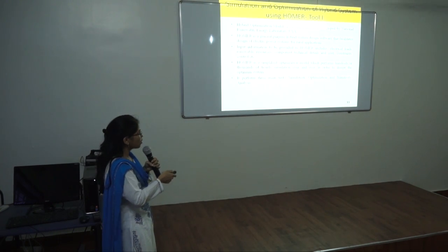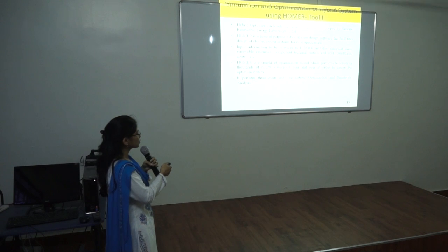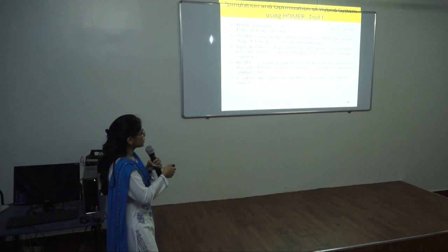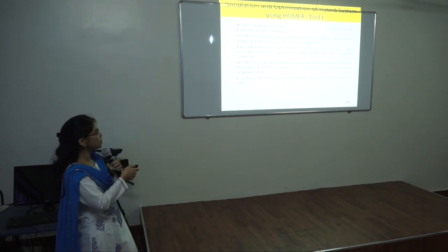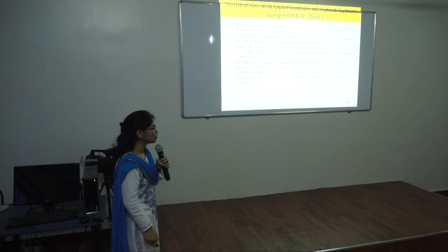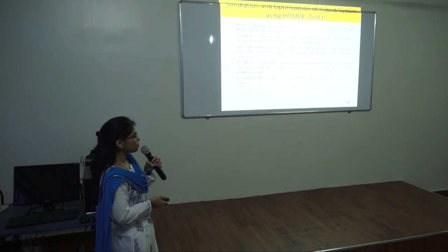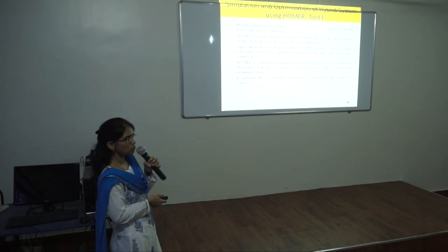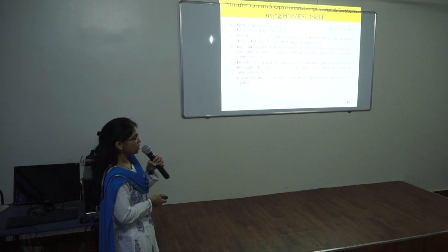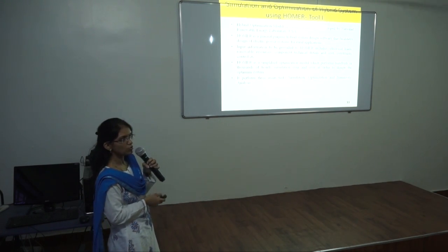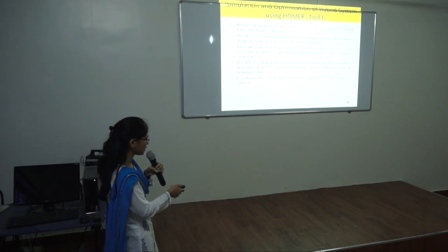By considering all parameters, first of all the system has been simulated by using the first research tool, that is HOMER. HOMER is the Hybrid Optimization Model for Electric Renewables developed by the National Renewable Energy Laboratory. The input information provided to HOMER includes electrical load, system components, resource input data, cost, constraints, control, etc. It performs three main tasks: one is simulation, then optimization, and next is sensitivity analysis.